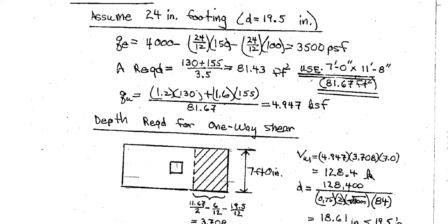Now you can provide here 12 feet to make it a round number, no problem. But as it is an edge column, boundary line may be a problem. So this is why the solution is becoming very careful. They are not giving more than whatever is needed. But you can provide here 12 feet to make it a round number. Your field labor or site engineer, they will love the round number.